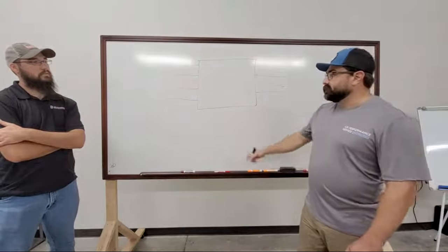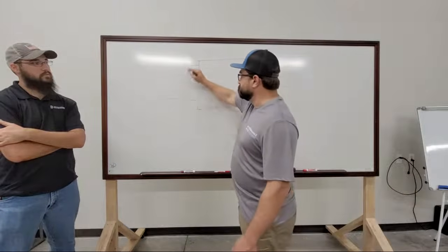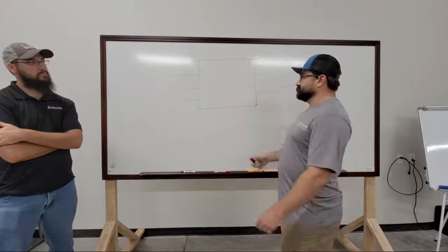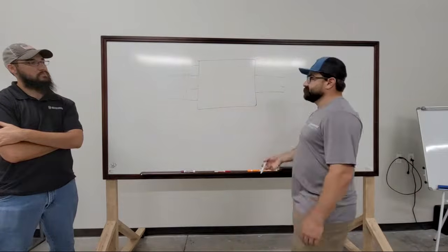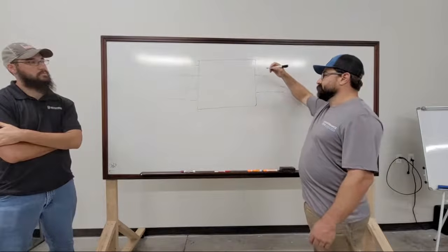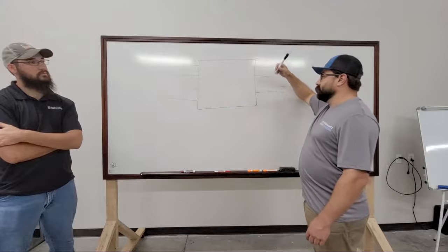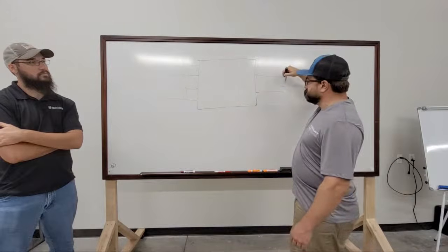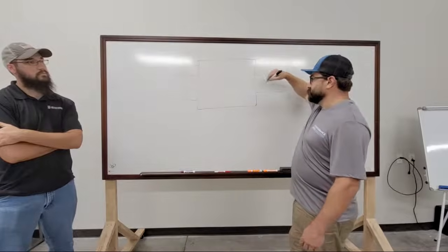Same basic thing, you have airflow pickups if it's maintaining flow, measuring velocity pressure, converts it to CFMs, sends out how much CFM you want. They also, some of them, actually most of them, don't care about the temperature coming in as far as controlling temperature.